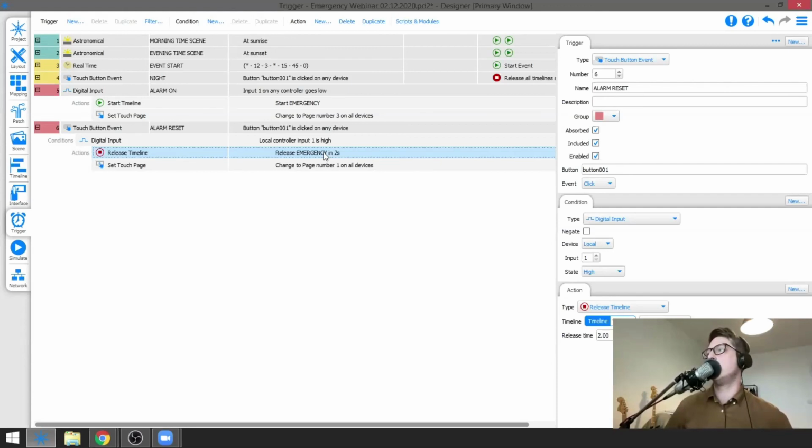Is Pharos not connected to this? If Pharos is not connected to a central power. So I guess that, for example, the situation when we are connected to a UPS or something like that. So no is the honest answer. You can power Pharos in two ways, and I have seen people sometimes make this mistake, and it's not recommended. But you can power Pharos with either PoE, power over Ethernet, or you can power it via mains. You cannot power it via both, or you shouldn't, because you could potentially short the device.